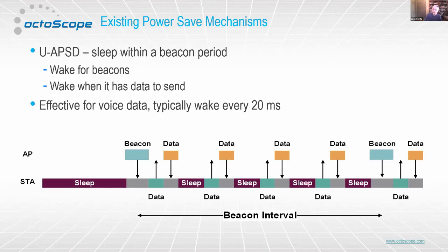What it did was it allowed the devices to go back to sleep and to send traffic even within a beacon period. The reason for this is that, since it was designed really around voice, and packetized voice tends to use a 20 millisecond framing time, you would get the device going to sleep, then sending and receiving these 20 milliseconds of voice information, going back to sleep and waking back up again to do another 20 milliseconds of voice.